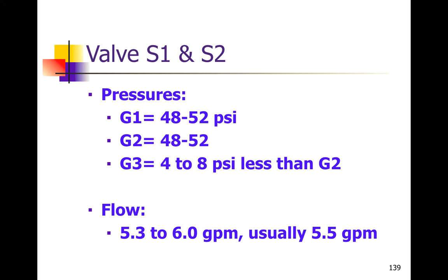Again, you should come up with these same pressures. If you don't, that means something's wrong, and you'll need to make a call or get a hold of somebody or figure it out yourself. Now there is a troubleshooting guide in the O&M manual that's posted on our website that will go through every single rendition of problem that you may have and tell you what you need to do to figure it out. Or call us and we'll walk you through it.